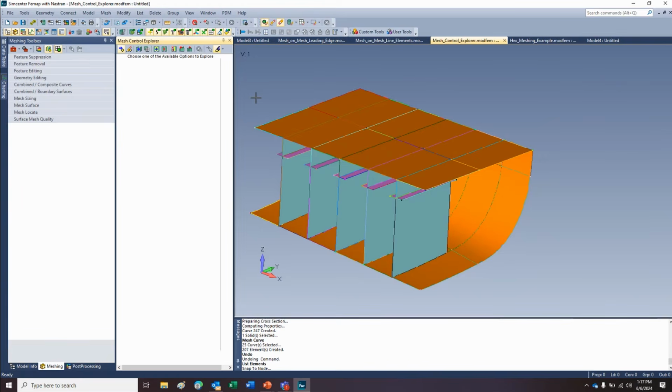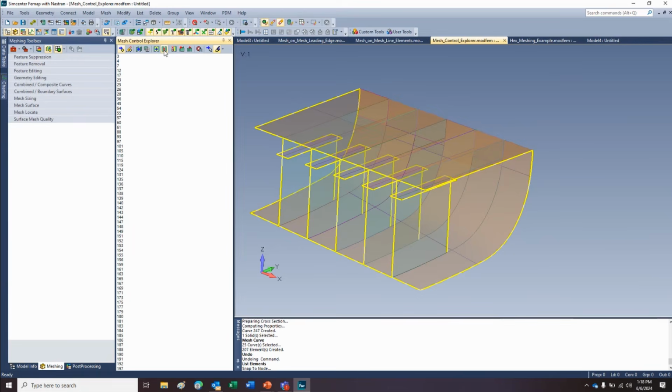For all of you folks who've had to try to non-manifold add 3,000 surfaces together, and then you get the one problem where it says, surface facets do not exist on the surface, and next thing you know, your whole geometry is corrupted. Well, what if you didn't have to do that to some extent? What if you could just say, hey, find me the paired edges. Actually, that's the free edges.